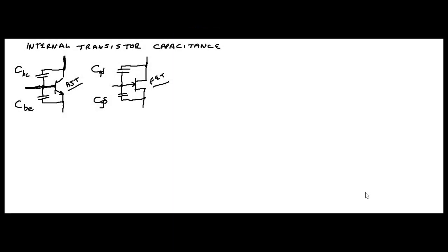Alright everybody, so let's start talking about high frequency. High frequency amplifier response, you have to think about, well, first off, let's back up. When you start having high frequency going through an amplifier, things start to change. One of the things that starts to impact the ability of your amplifier to amplify a signal is the internal capacitance of the device.